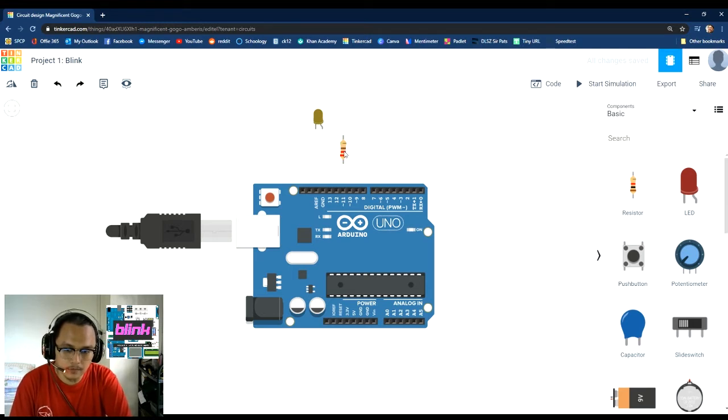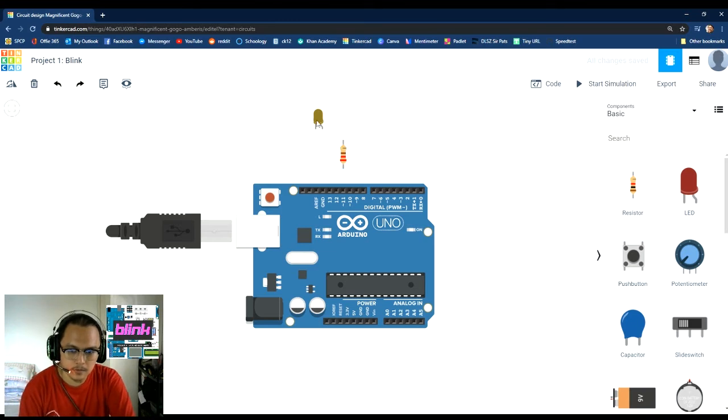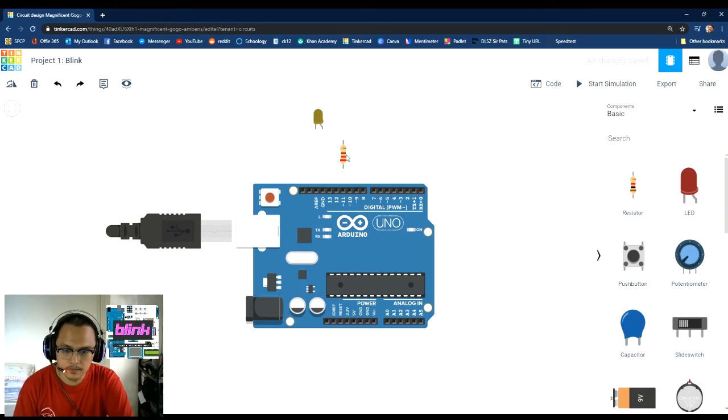So that voltage carries a big current. So we need to slow that down just a little bit to prevent damage to our LED. Thus, we need to reduce the current. So we are going to use a resistor. So resistor is important, and in all of your future circuits and challenges, do not forget to include a resistor.